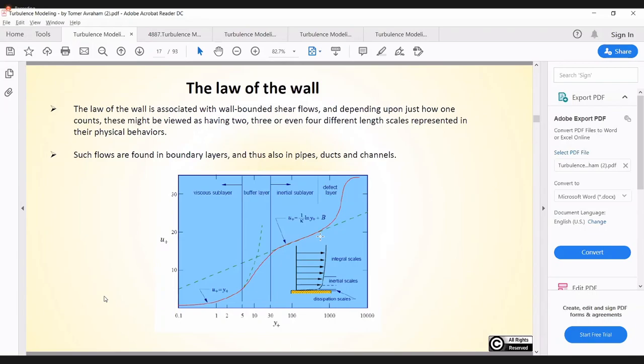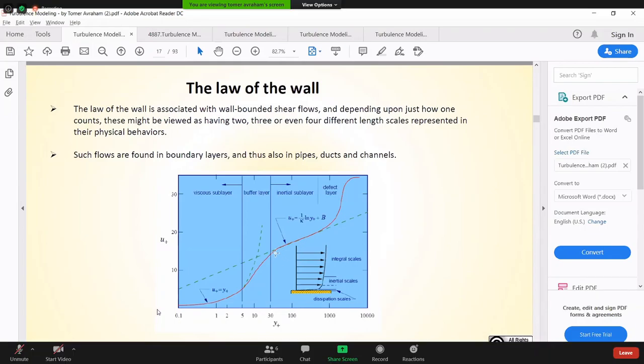It depends on the Reynolds number, okay? If the Reynolds number is very large, it could be 2,000, 1,000. For turbomachinery, sometimes it's around 400. It doesn't mean that we don't have to have the same resolution here. We have to have the same resolution. If we don't have the same resolution, we will get bad results. So you need to pay very good attention.